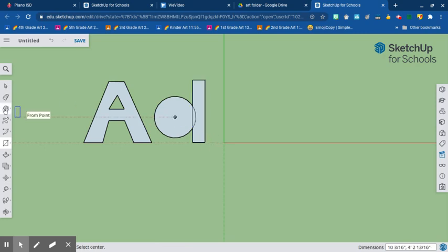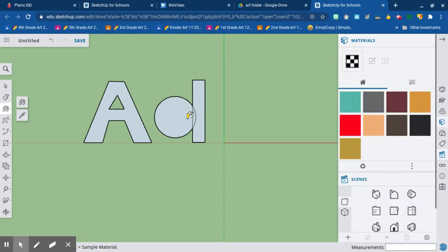And then I'm going to use my erase tool to come over here. Oh, erase tool, not materials. Erase tool to erase those two lines. And then I can still draw a circle inside. Now, if you're drawing a circle inside, find the middle first, not the edge. Find the middle, click one time, drag, click, and then you have a shape that you can go select and delete. I'm going to select and just use backspace to delete.